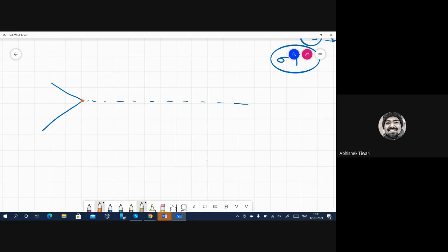If you go away from it, whatever stress you are applying, that much stress will be felt, because you are too far away from this object. And you see that the stresses decrease, not in a linear way, but in a non-linear way, as you go away from the source of this singularity.